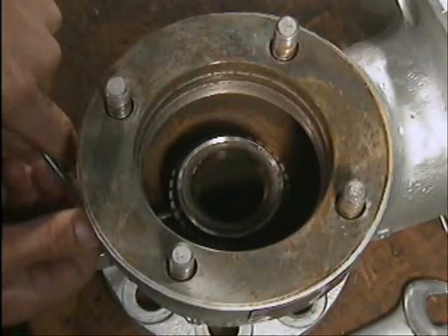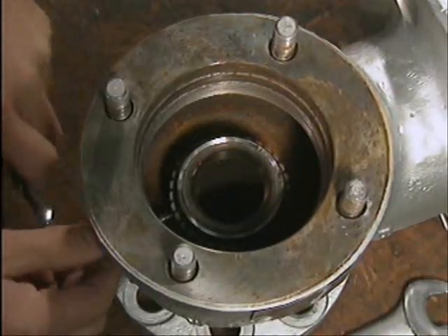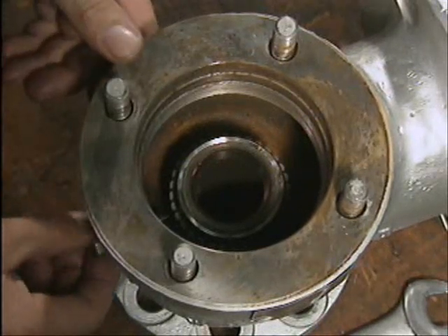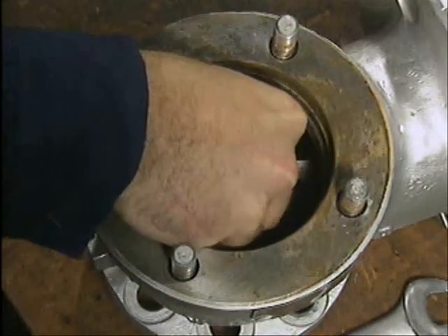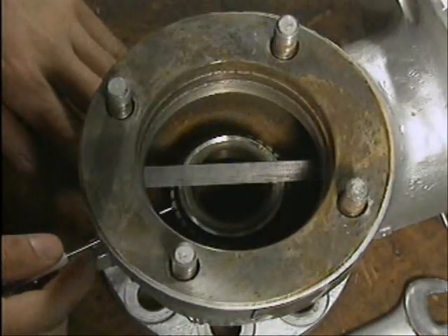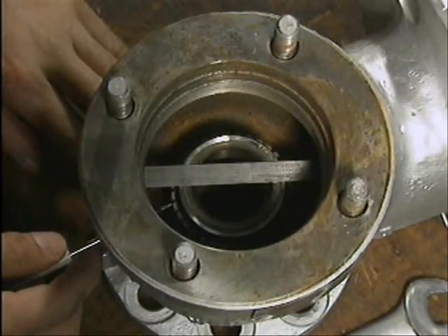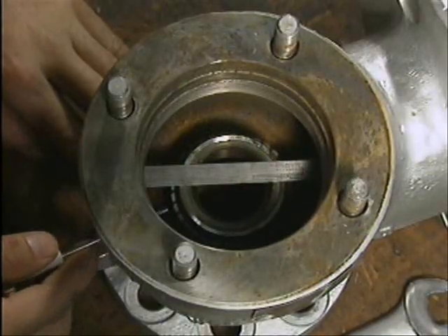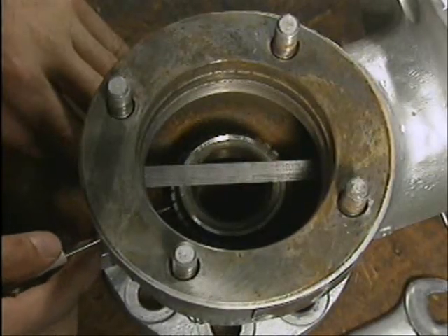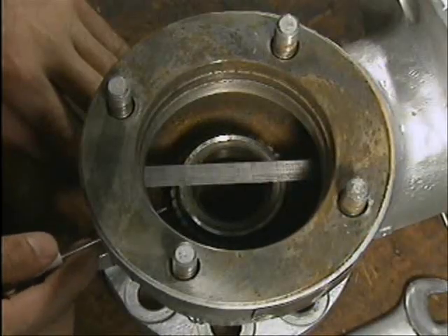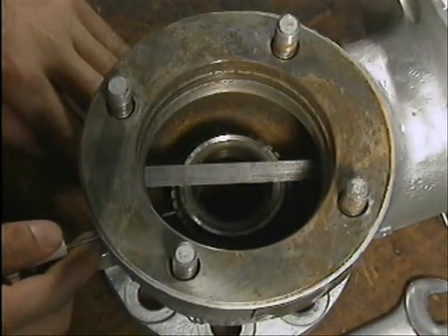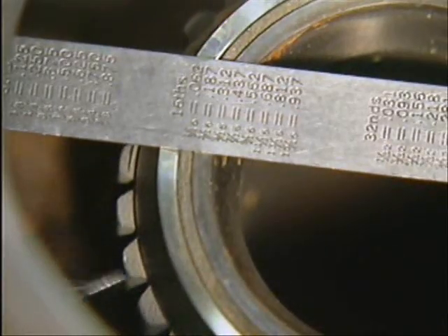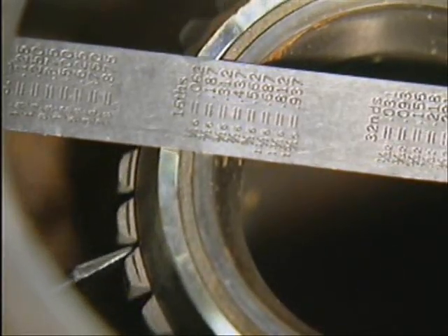Now repeat these steps to remove the locking pin for the lower adjusting ring and measure the exact position of the ring. Insert a screwdriver through the lower locking pin hole and unscrew the ring by turning each notch past the pinhole until the ring is flush against the rigid rule that was placed on the valve seat to take the measurement. Count each notch as it moves past the pinhole while the ring turns.